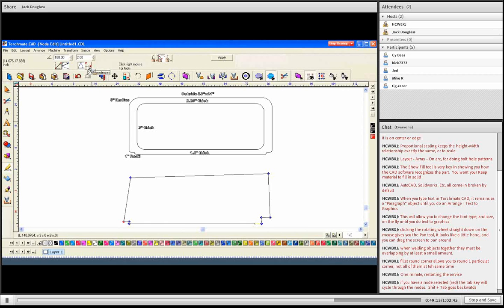So in this case either one works, and really for any part, any of them work. But from here, we'll hit tab and go to the next node. Basically, this node up here, which if this is 21 inches and less 3/4 of an inch there, we know that we have to go up 20 1/4. And we're not going left or right any, so 0.